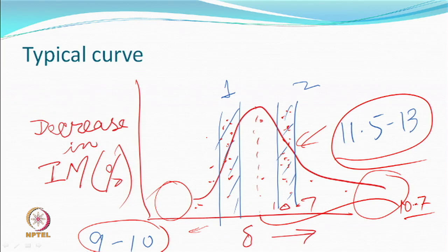And what they had measured was solubility and decrease in the initial modulus of the material. So, fiber is there. If the solvent is plasticizing, it is entering, so the modulus will go down and it will become a pliable material. So, you measure the modulus. You do a stress strain curve and then take the modulus at every point for different solvents, obviously treated at a certain fixed time, and then you plot this curve.